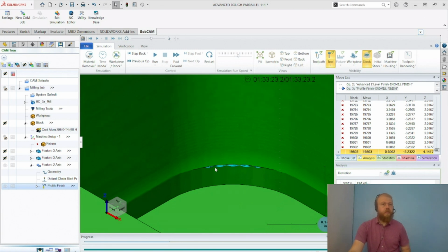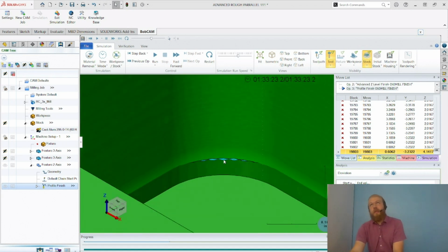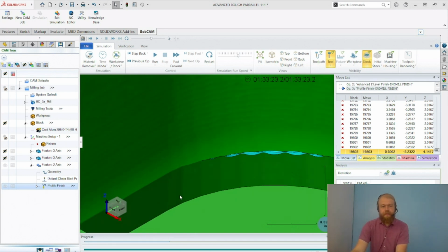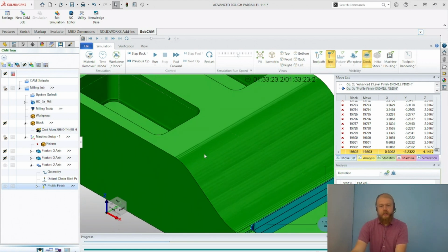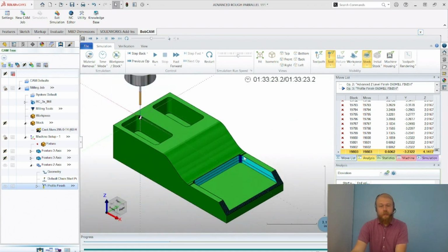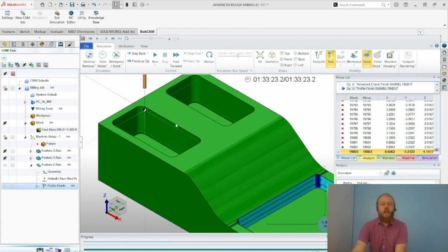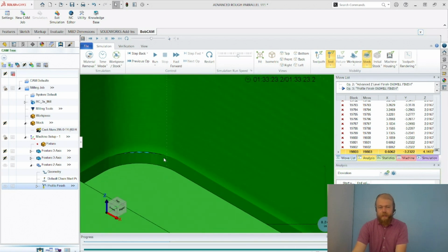With the ball end mill, we used a 1/4 inch ball end mill, so if you wanted to get any more material than this 1/8 thou, we could use maybe an 1/8 or a 1/16 inch ball end mill and focus right on the corners here with a couple more passes. Then the ball end mill cleaned up this area as well. We could do a profile along with the pockets here, along with this pocket, as well. But yeah, a lot of great options here to compute the toolpath and have everything cut to size here. If everything looks good, we can close out of our simulation.